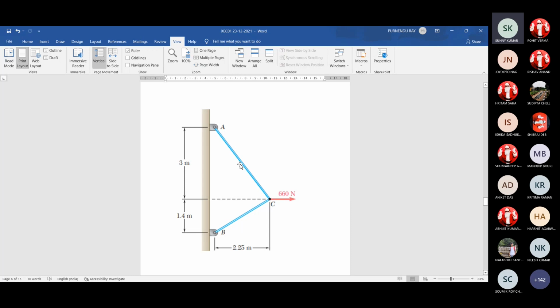Hold one set square, matching one edge with this straight line AC. You hold it firmly, then you bring another set square, place it freely, matching that edge, and then you slide it with this firm edge of the set square held in your left hand. When you slide it, the sides will be parallel to its original position, and we can shift this straight line to some other location.